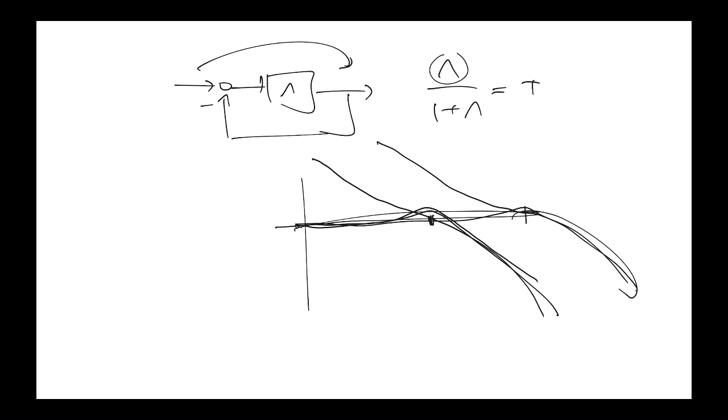Yeah. Yep. So I'm not trying to say the 3 dB point, blah blah blah. That's kind of too much detail for the message I'm trying to get across, and it doesn't really matter, right? We're trying to understand what happens when we move one thing in terms of the effect on another, right? So moving the crossover frequency to the right will extend the range of frequencies over which the complementary sensitivity function is 1, assuming we have sufficient gain in the open loop transfer function at frequencies below that.